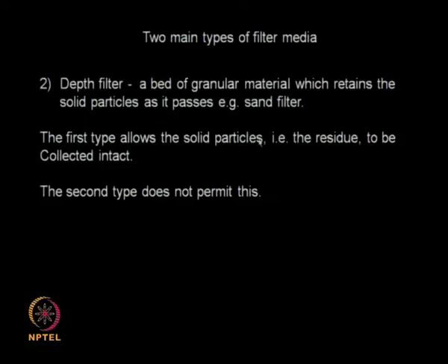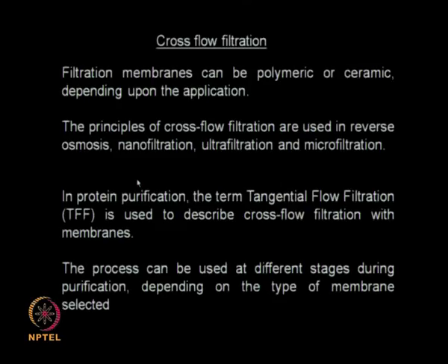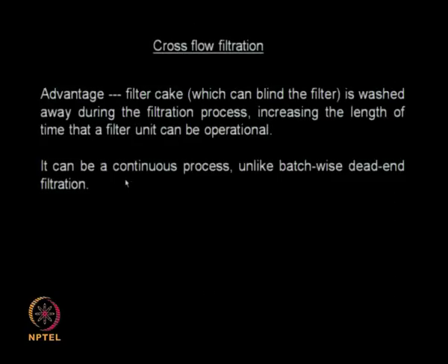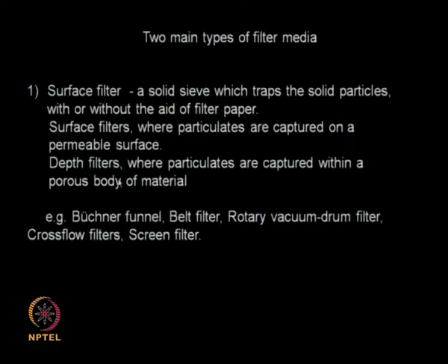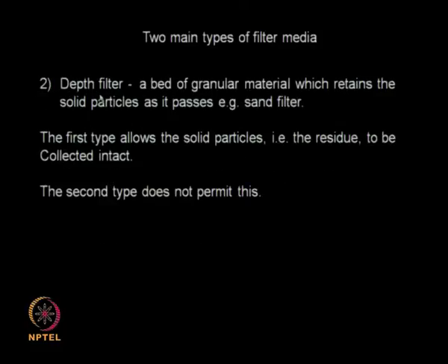The surface filter allows the solid particles, that is the residue, to be collected intact, whereas the depth filter does not allow you to collect the solids intact. So here we are more interested in the liquids, the amount of solids that is present is not also very large. So in that situation depth filter is ideal.